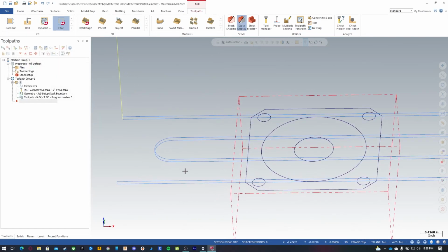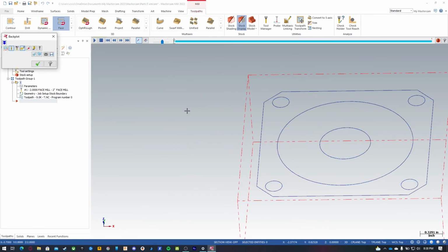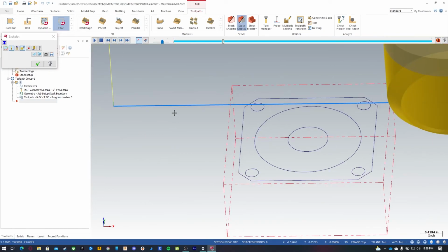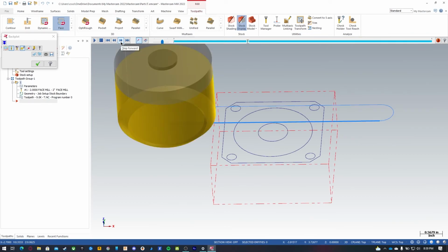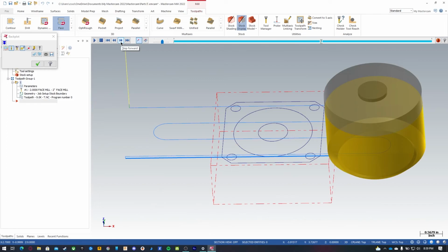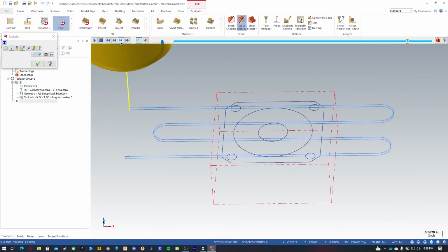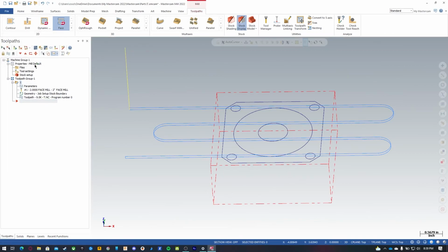Now if you take a look here, we're going 100 thou, and we'll be able to do a finish pass at 10 thou, and we're stepping through, and you can also press S on the keyboard, and then it drops down a little bit further and cuts across without having to wrap it back over to its initial point.